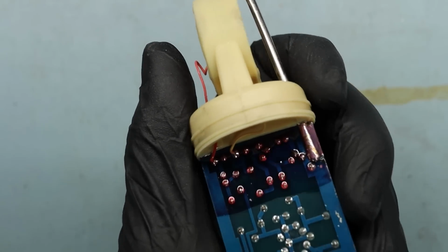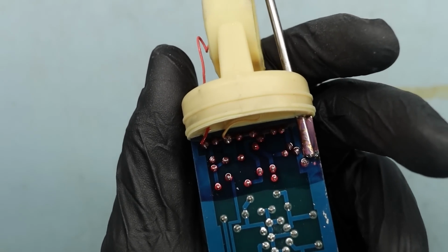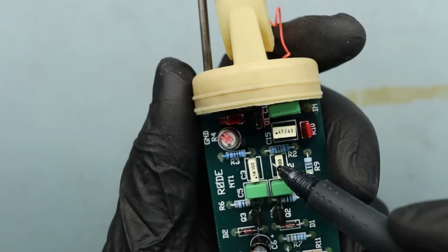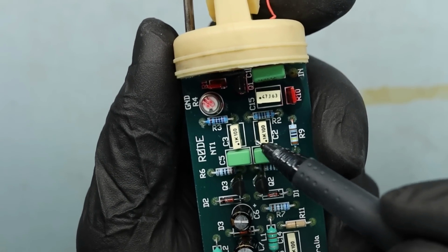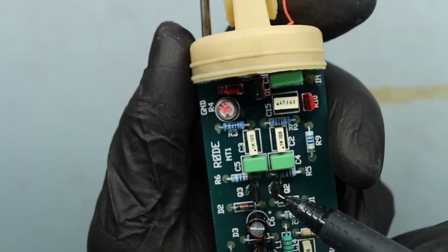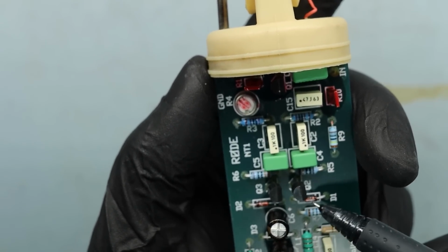What's also interesting is they've conformally coated this, you can see kind of a shimmer there. Anytime you have low noise stuff like that JFET amplifying with a large gain, you want to keep the grit and grime out of there. There's a lot of symmetry here. We've got some capacitors that we saw in our schematic that are part of these 2 common emitter amplifiers. And we have our Zener that helps regulate the voltage.